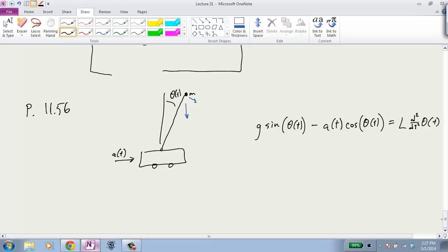Now we want to control such a system that has these dynamics. The first thing we're going to do, after noticing that this is nonlinear, you see this is a sine of our signal, theta of t. We don't deal with stuff like that, right? We're learning about controlling linear time invariant systems. This is nonlinear. But I mentioned that one of the tricks that's used to turn a real system into a system that we have the math for is to linearize. So you linearize around the point you want to operate, and that point is the vertical point. So we're going to say that the system, for very small theta, acts almost linearly, and if you do the Taylor expansion, you get,